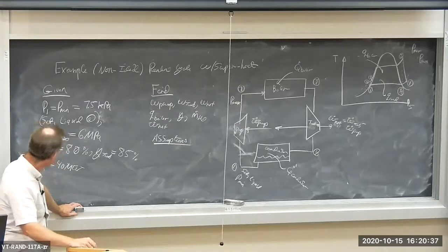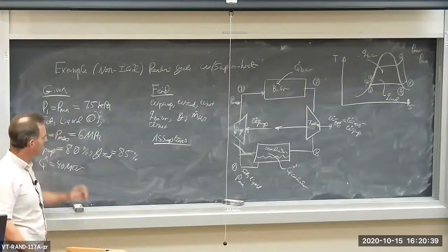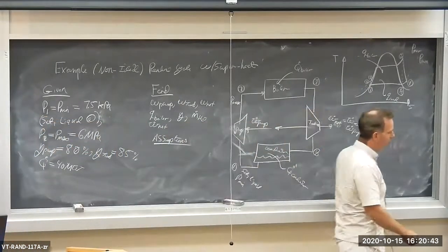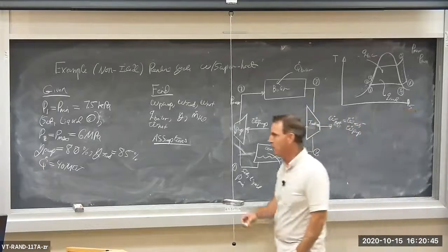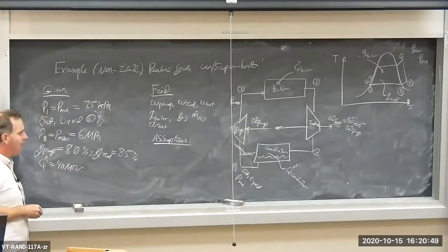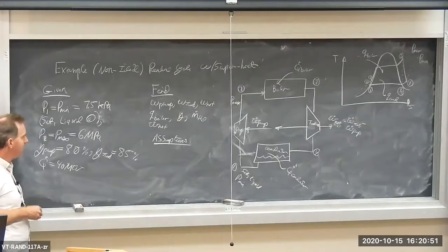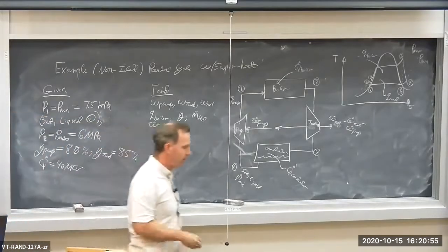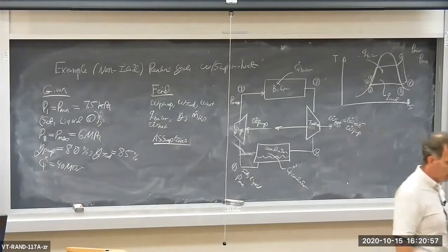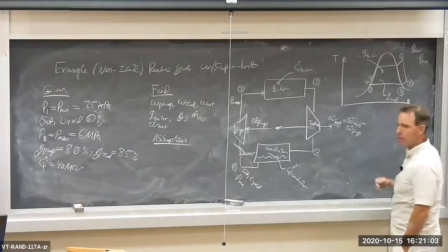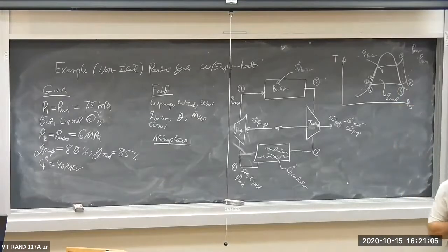Let me give you some numbers here. The minimum pressure in the cycle is 7.5 kilopascals. So we start off as a saturated liquid at state 1. The maximum pressure in the cycle is 6 megapascals. So we start off below atmospheric, less than 1/10 of an atmosphere, very low pressures. Basically, that reduces the condenser temperature when we have such a low pressure.